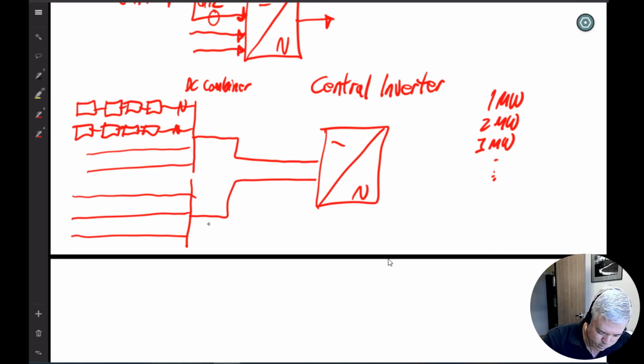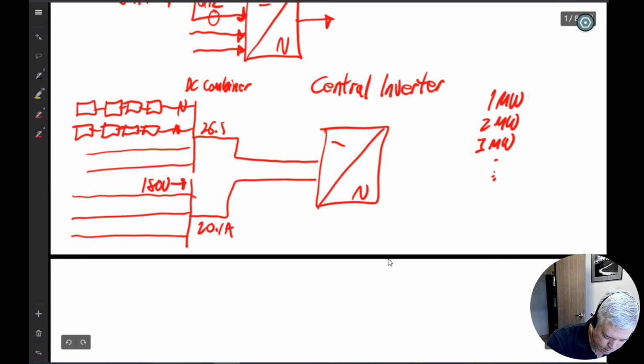Notice that in our case we did 4, and we said that they were 180 volts in. But we said that the 6.7 amps was fixed. Well, when you combine them up in parallel like this, the 6.7 is multiplied by the number of strings that you put together. So in this case we have 3, so we have 20.1 amps that would be going into there. And on the top one we had 4, so we would have 26.8 amps going into that one.